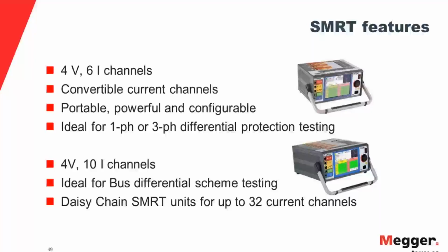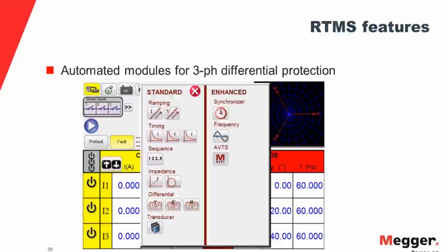So you will verify that. The relay operates for a harmonic value less than the settings, and restrains itself from operation for a harmonic value higher than its settings. So you're verifying, it's pretty much a go/no-go test. As I mentioned before, you have to do it on individual windings as well.